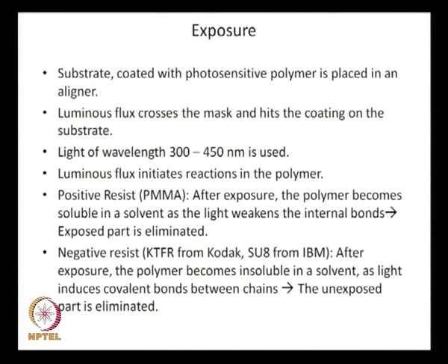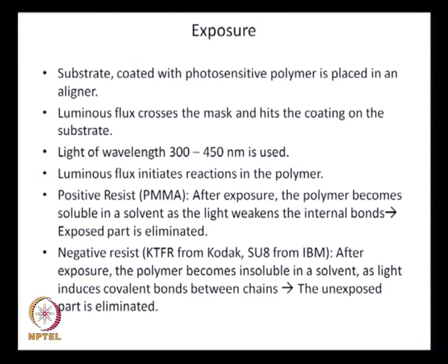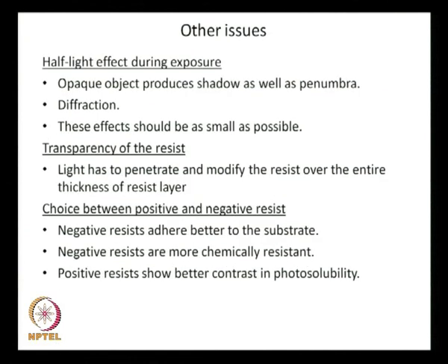So, in one resist light is breaking down the chains, and in the other resist light is creating the chains. That is how nature works. So, in case of negative resist the unexposed part is eliminated, and in case of positive resist the exposed part is eliminated. I hope this is clear to everybody.